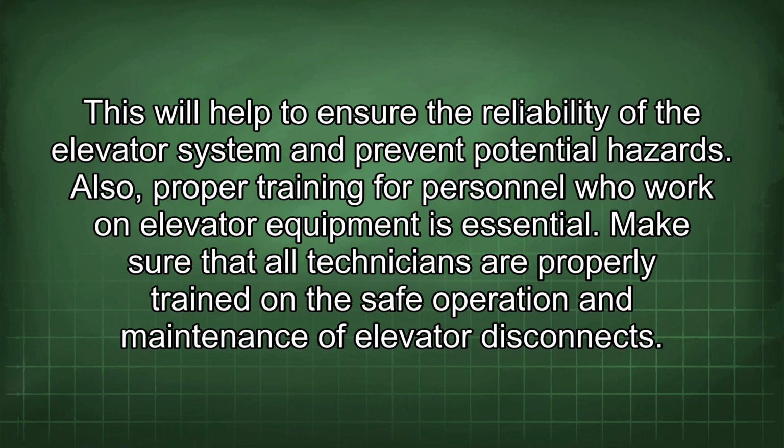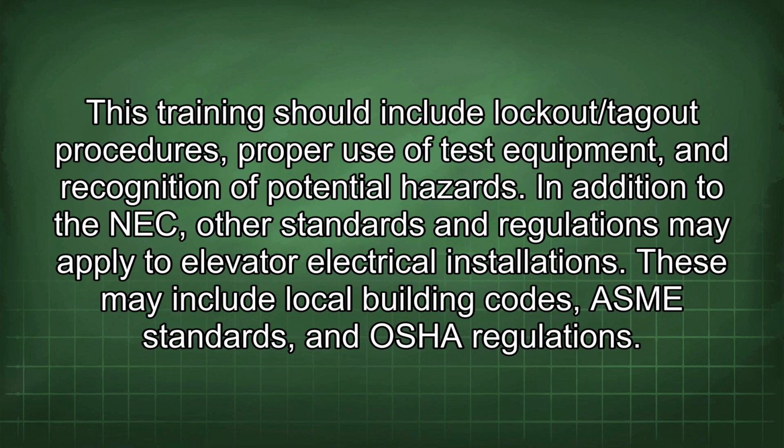Also, proper training for personnel who work on elevator equipment is essential. Make sure that all technicians are properly trained on the safe operation and maintenance of elevator disconnects. This training should include lockout/tagout procedures, proper use of test equipment, and recognition of potential hazards.